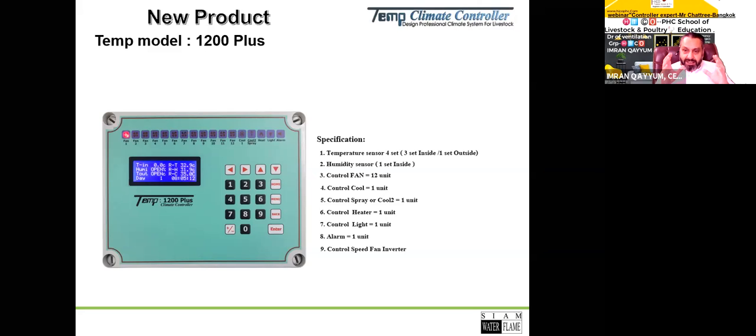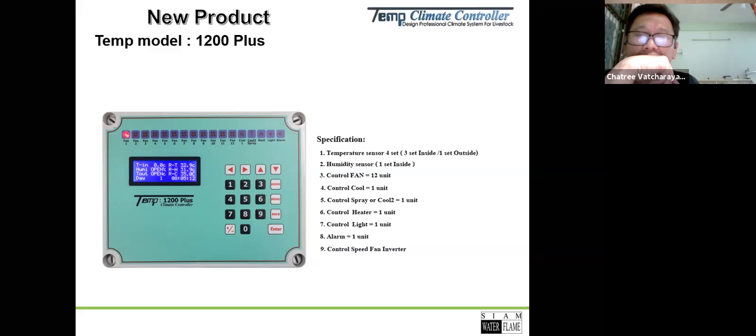So you just set your house on negative pressure and adjust your inlet opening percentage, and then your control should be on the low pressure control system or inlet opening or flap opening system. That's better. Yes, you're right.